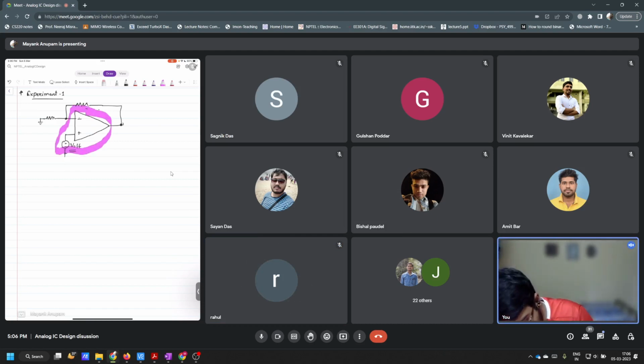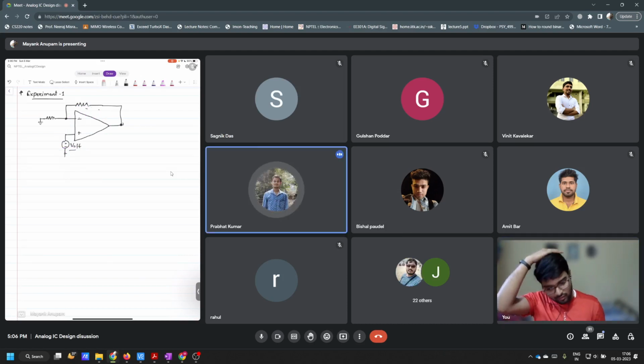So what is accessible to you is the terminal which is outside of this, isn't it? This is the terminal that is accessible to you. You can add anything here. This was Vs, by the way. But now let me ask you, if you have to calculate V offset, if you have to find the effect of offset voltage, how will you do it? What does your intuition say? What does your common sense say? Short circuit the input. Correct.